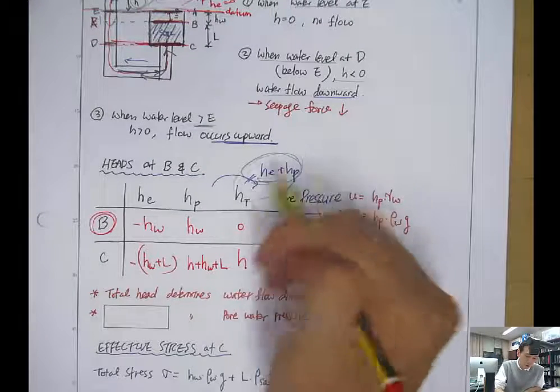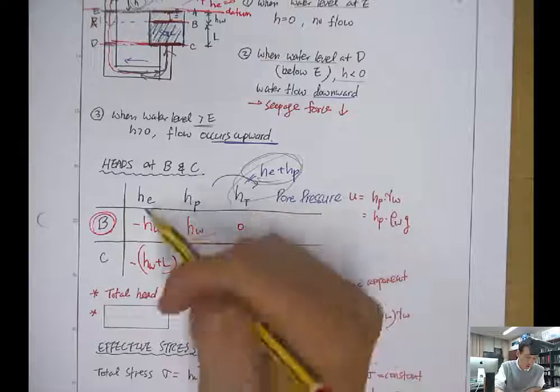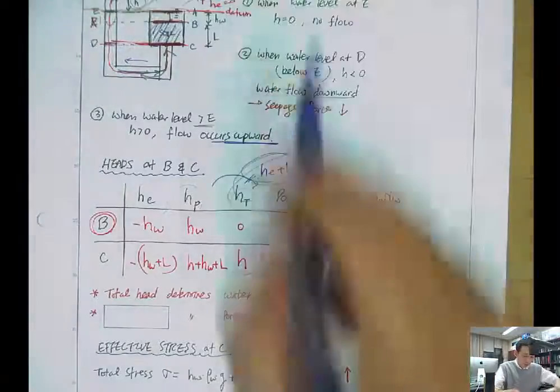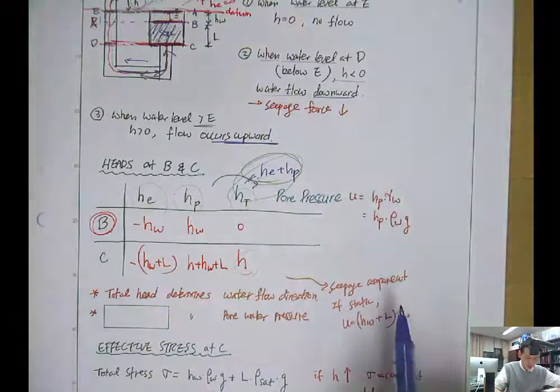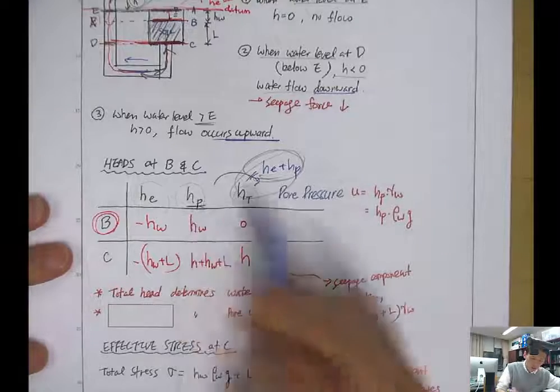So from this relation, because you know the HT and the HE, you can compute the HP. So then pore pressure can be calculated using the pressure head.